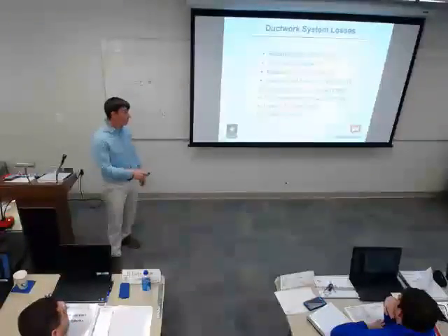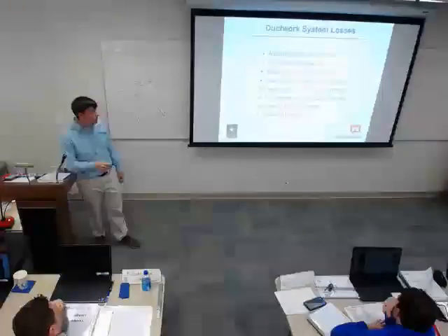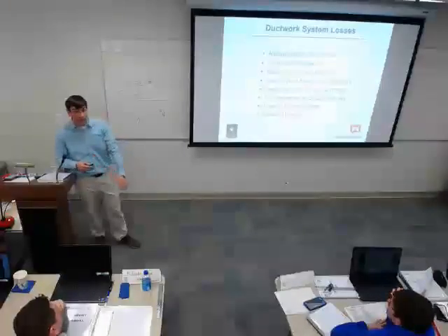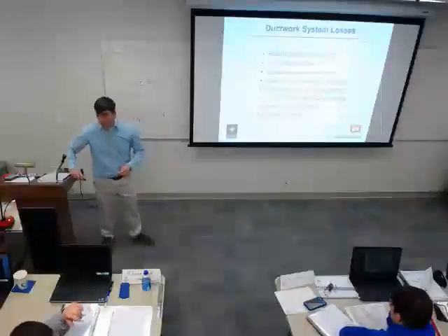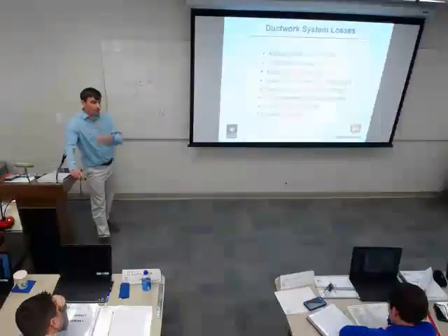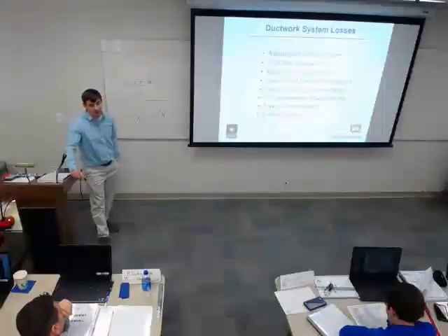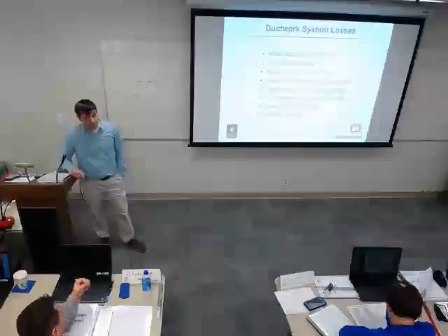Correct, and if you start having to add a bunch of these, you also need to call your designer back up, because he probably didn't account for a whole bunch of extra elbows that are going to add static. And those are worse, besides 90s, because the flow coming off the 90 isn't fully developed. So his calculation for the ductwork pressure drops is going to be off. It's only a question of how wrong.